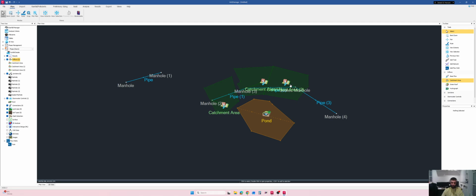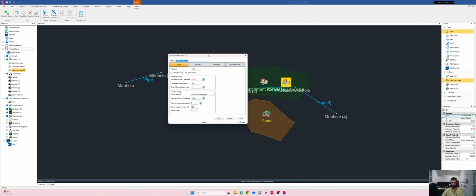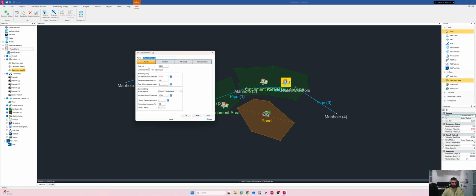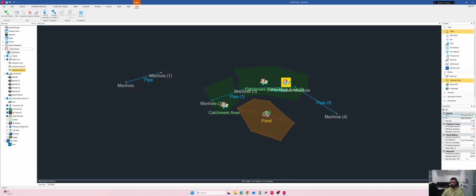You can just double click this one. This will also have the area, like this is 0.23 hectares, then the volume runoff, then the time of concentration. We will go into detail in the upcoming videos. And then if you want, you have the junctions, that is manholes, that you have seen. Here you can also have the junctions like manholes, and you can also use the right tab.